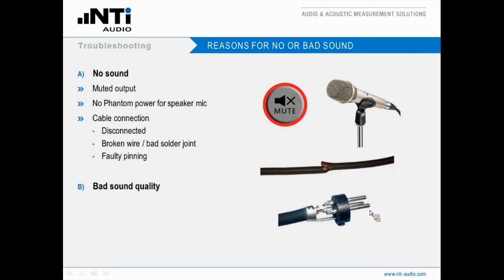Then we have a couple of reasons for bad sound quality. One of them would be a defective device that is causing audible distortions in your system. Another one would be that you have improper settings. So you have an overload of the input stage, for instance, which is causing clipping in your system.